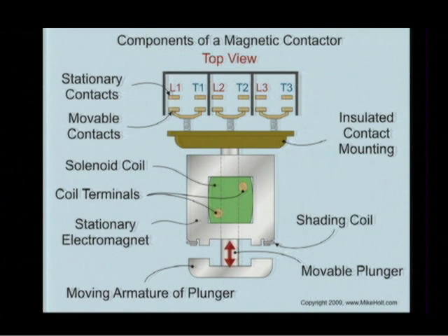It requires the springs to come open and so on. So the mounting position is important. So you're saying I might take a contactor and not be aware of this, and mount it on top of something, and gravity might close those contacts. Yes.